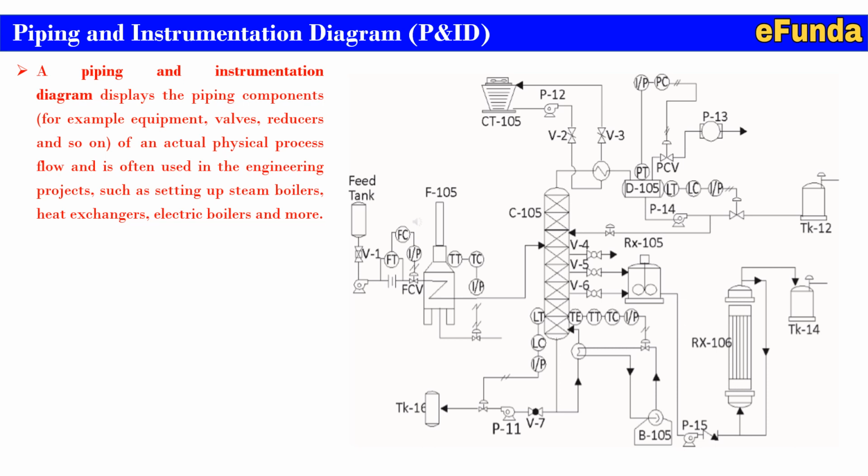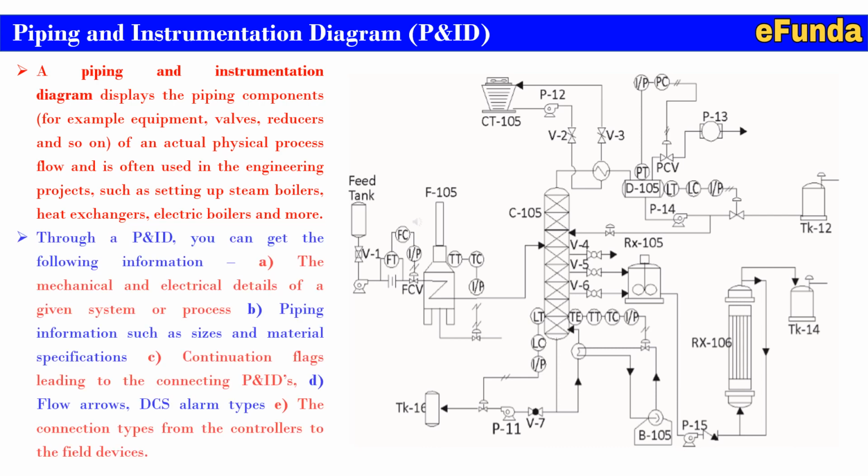pump section, where the exchanging level is measured through the temperature and the respective TCVs are controlled. This is how typically all the instruments required for accurate control of the entire plant are shown on the P&IDs. This is how it is typically covered.